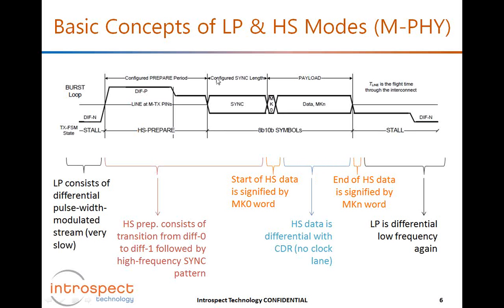And the reason that the M-PHY standard requires a very high frequency sync pattern to play on the left here, unlike D-PHY, is that in M-PHY there is no clock signal. So M-PHY operates based on CDR, on embedded clock. And because it operates on embedded clock, for it to reliably receive data in this section here after marker 0, the CDR has to train. And so we need to give the CDR enough time to train on the incoming data before producing the data. And so that's really why the sync pattern exists here.